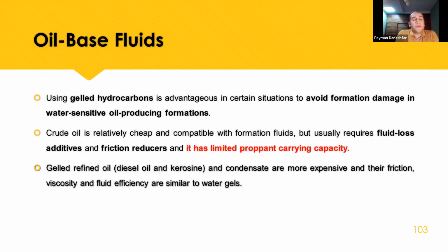Another one is about the oil-based fluids. For the oil-based fluid that I told you before, oil-based fluid is okay for formations that have more clay mineral. But when we use a water-based fluid, we can use some additive such as KCl for clay control. But the oil-based fluid has some problems: it is expensive, and it's not good for the environment.